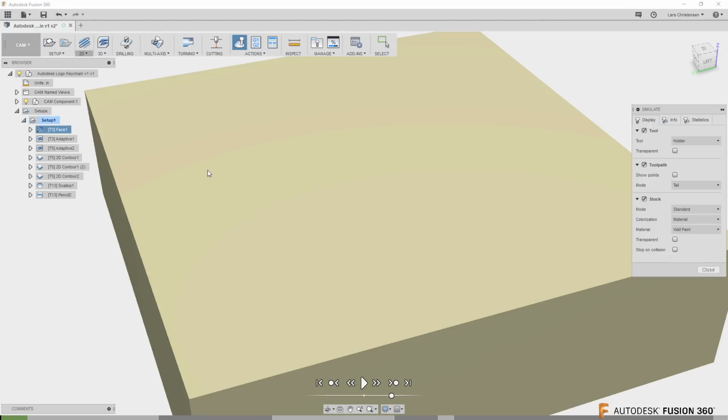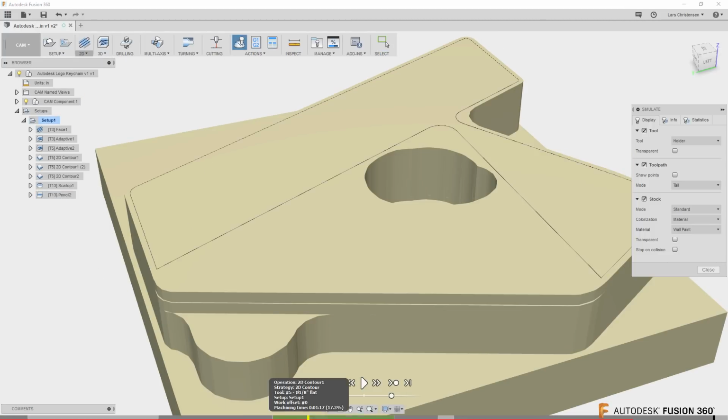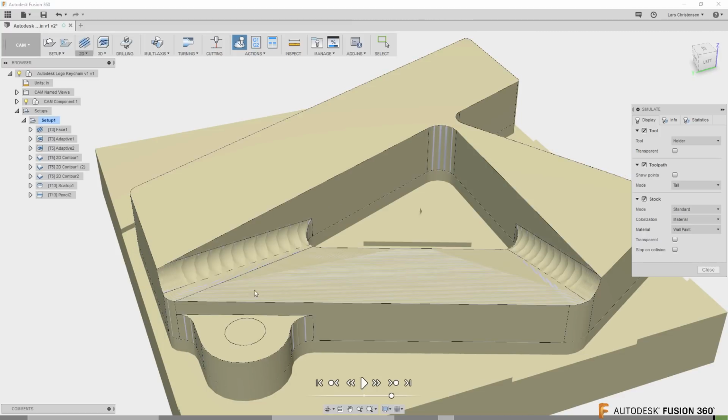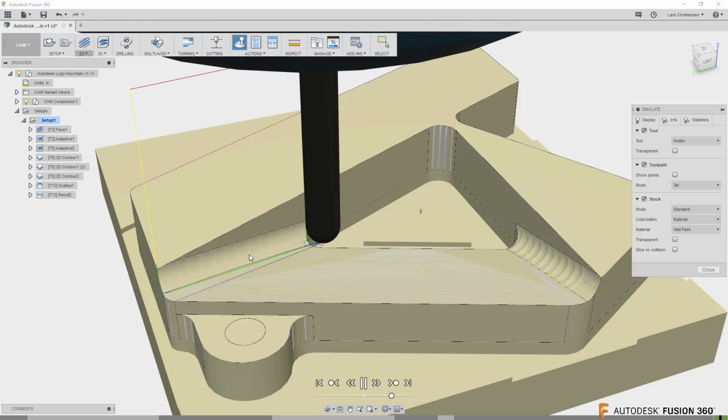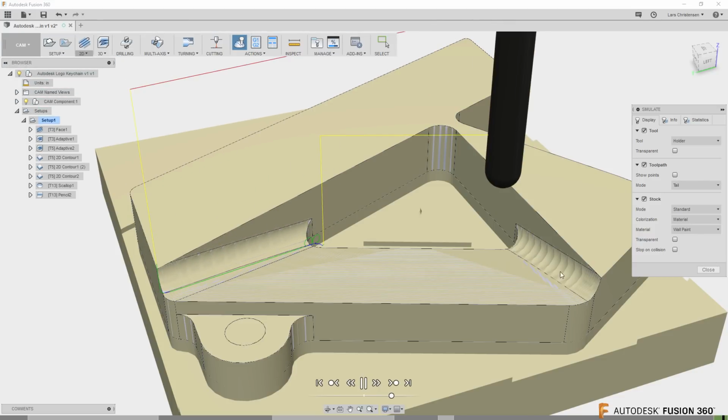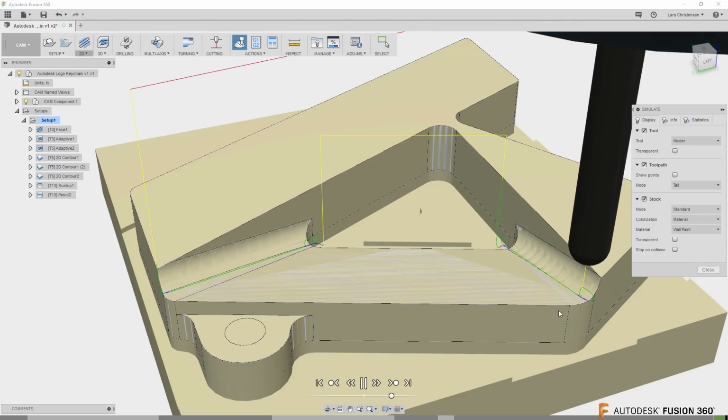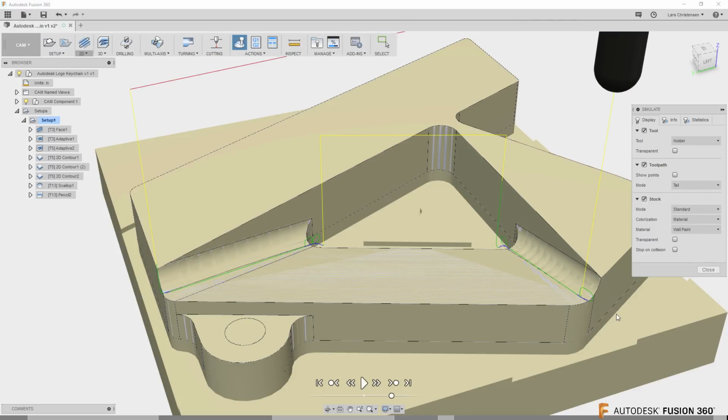So if we go in and simulate this, you will see that the last tool path here is just going to come in and kind of like pencil, like you took a pencil and just smooth out where we have these almost gouge areas right here. This would probably be somewhat my beginning start point if I was going to program this part here.